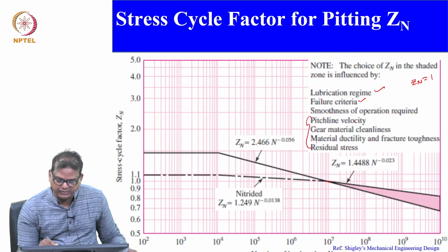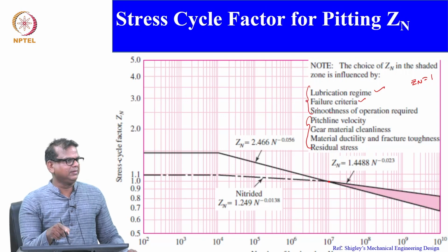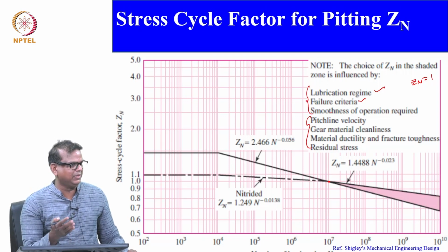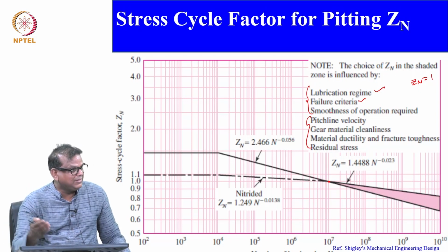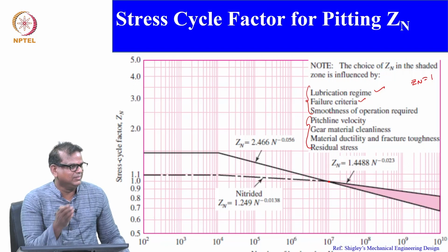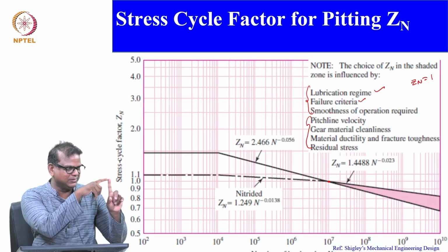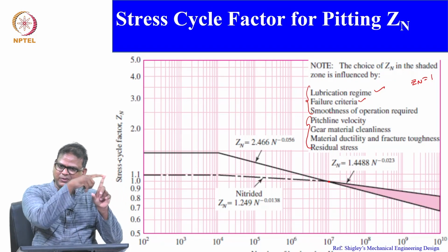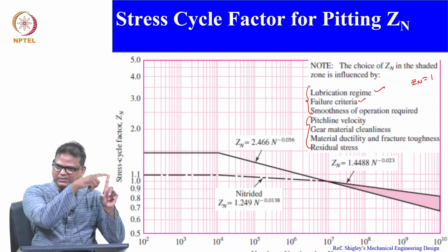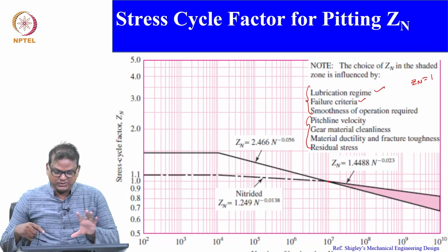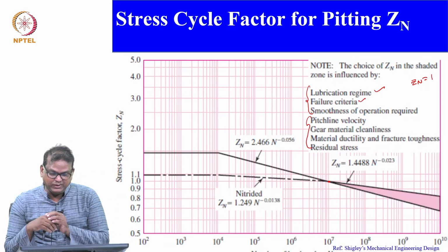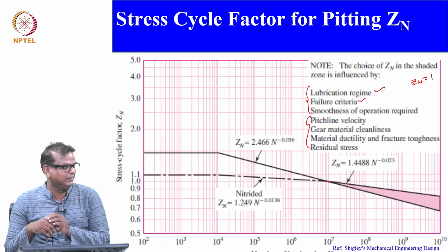These are already there for bending. Additionally, you have to look at, because this is nothing but the wear failure also, right, wear failure or else contact failure, pitting failure, are related to lubrication. The bending has nothing to do with the lubrication, this is about the stress. So the tooth breakage is on this aspect. So that is why the top 3 are very critical for pitting,